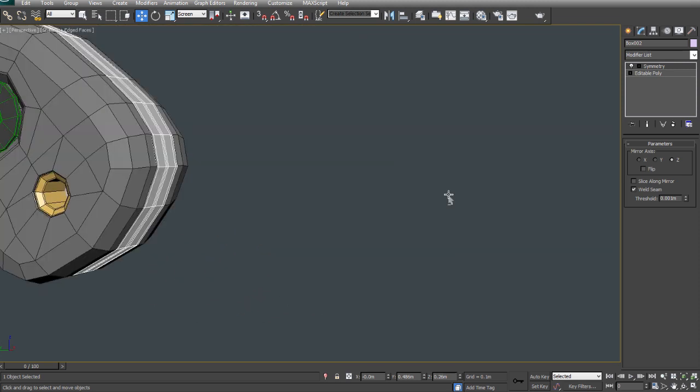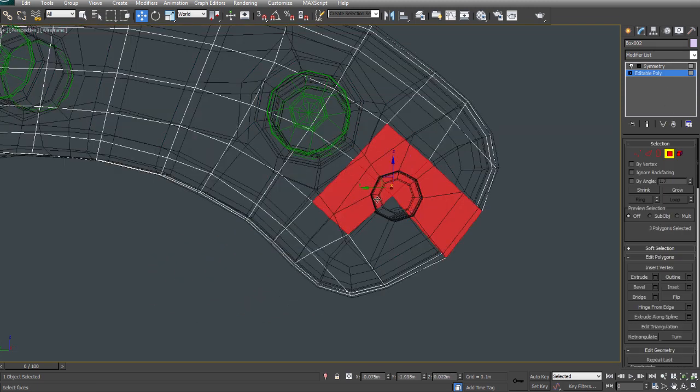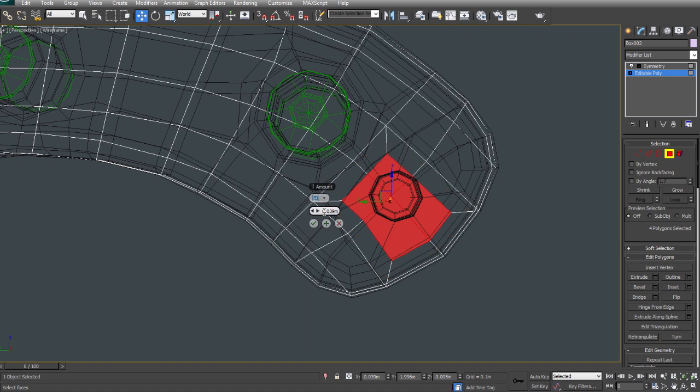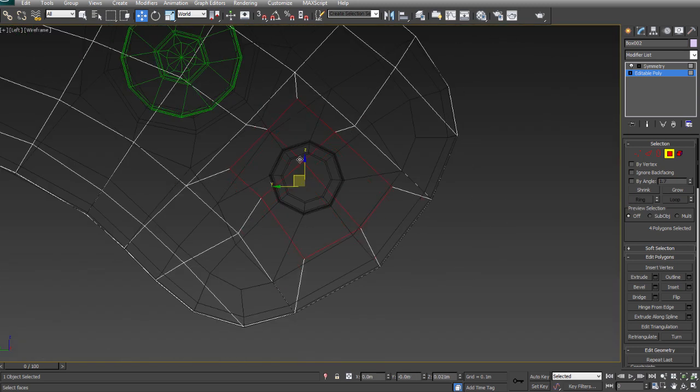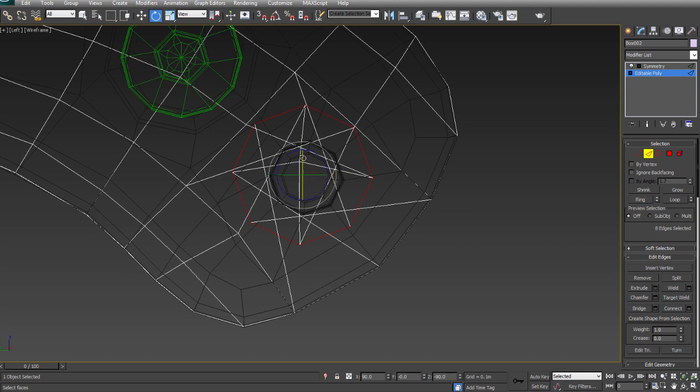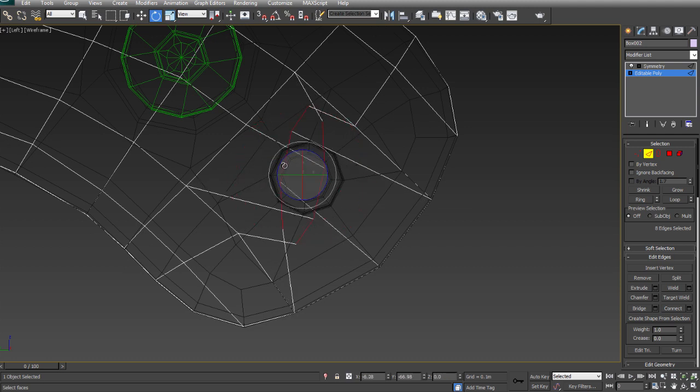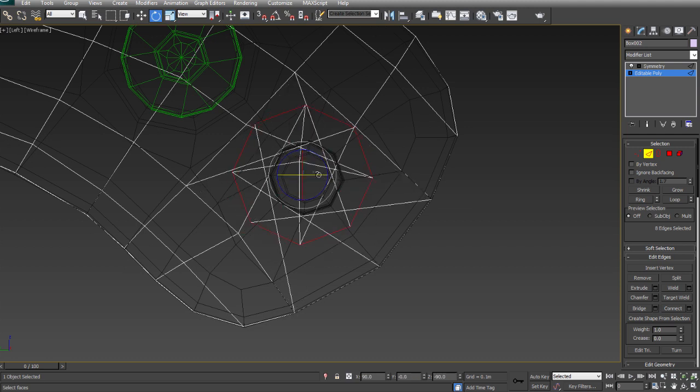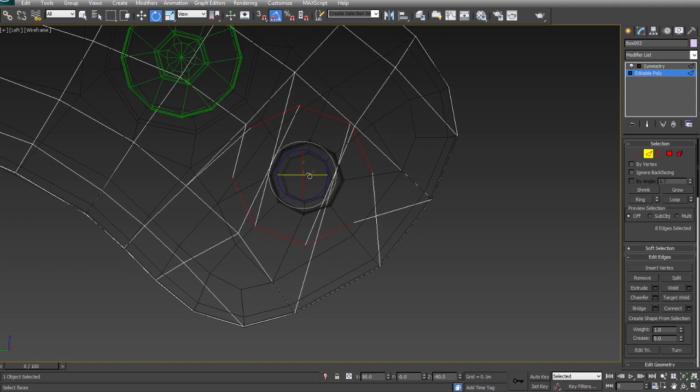The reason for doing that is simply so the low poly matches the high poly as accurately as possible. And we've got screws on top as well, so the low poly is trying to represent the high poly handle and the high poly screws all at once. So we need to make sure that the low poly is almost shrink wrapped to both of those surfaces at once, rather than maintaining the curvature of the inside of the screw hole.